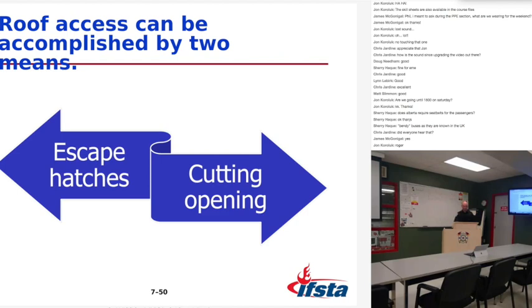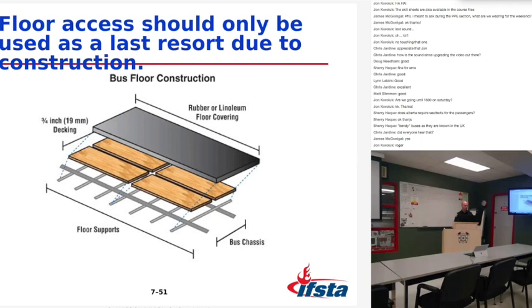An air chisel only cuts 1 layer at a time. Double amount of the time needed. And plus it still has to go through those ribs. So the air chisel wasn't my favorite choice. The reciprocating saw probably does a better job because it goes through all 3 layers. Yeah, you can see on the red truck out back on the weekend that we tried to do the sides, and you can see where we ran into the braces. Yeah. The air chisel doesn't like those.